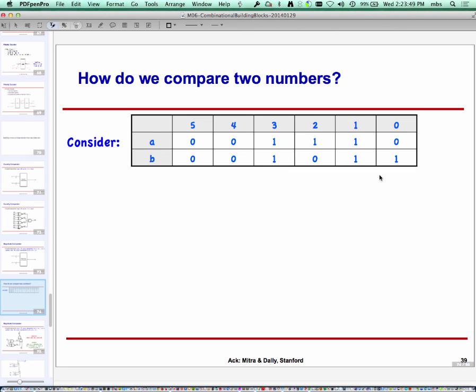Or another way of saying it: if I pick my numbers 172 and 241, let's say, and we start from the right. Units place, 172 is the winner. We come to the tens place, and still 172 is the winner. So we go to the next stage, and now we see that 241 is the winner, so we say 241 is the winner. We can apply the same logic from the other direction, and that's what the circuit is doing. Instead of coming from the MSB, it is coming from the LSB.